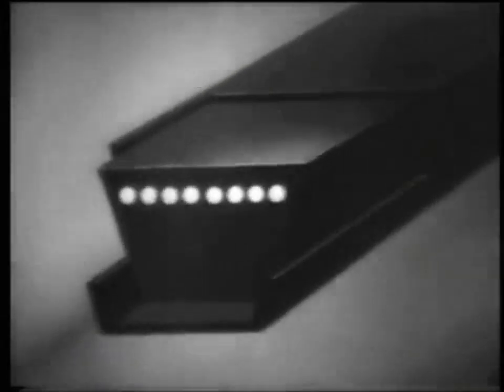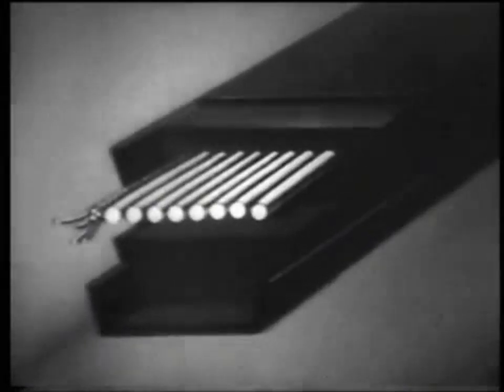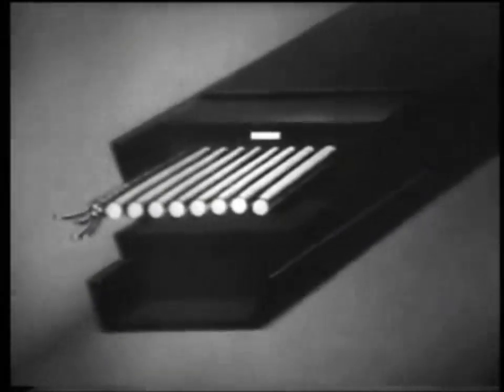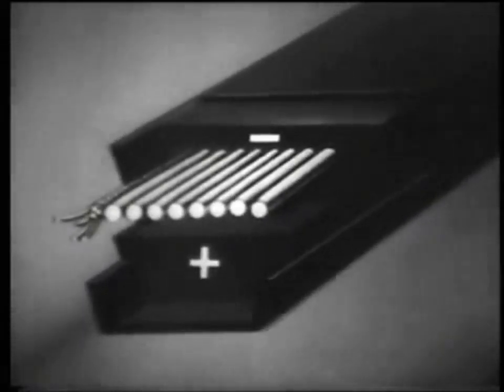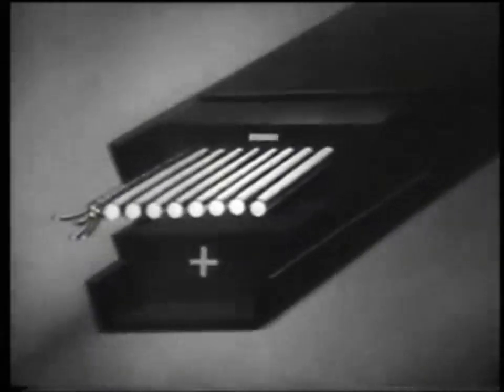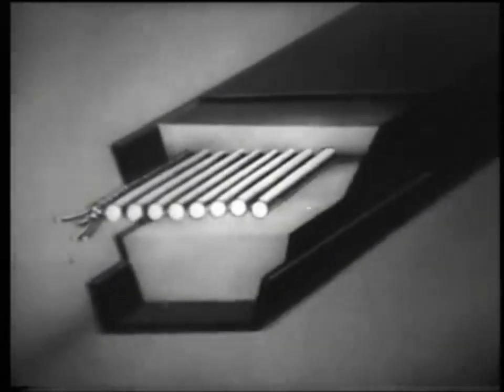The outside of the cord is wrapped in one or more layers of rubberized wrapping fabric. Rubber pads are located above the bearing layer in the stretch zone and below it, in the compression zone. This design gives good damping properties. Cord belts are more flexible and durable, and provide greater efficiency than cord fabric belts.